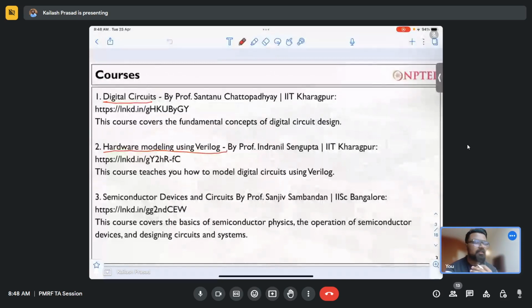Currently I think the latest technology is 5 nanometer, and 4 nanometer is already out, and 3 nanometer technology will be out in maybe another year by Samsung and TSMC. But the thing is, what's ahead, right? Intel has shown that we are going to 1.8 nanometer, that is 18 angstrom. And apart from that, I think Samsung has shown that they will be going to 2 nanometer, and all of this has new kinds of devices. They call this the complementary field effect transistor.